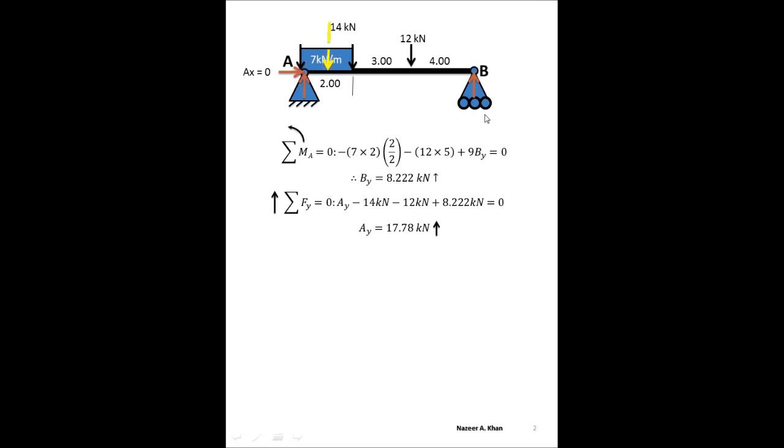We're going to have 3 sets of terms. Terms are separated by minus and plus signs. So we're going to have 3 sets. The equation is summation moments about point A is equal to 0, and counterclockwise rotation is considered to be positive. That's what that is telling us. Okay, let's go and create the magnitude.